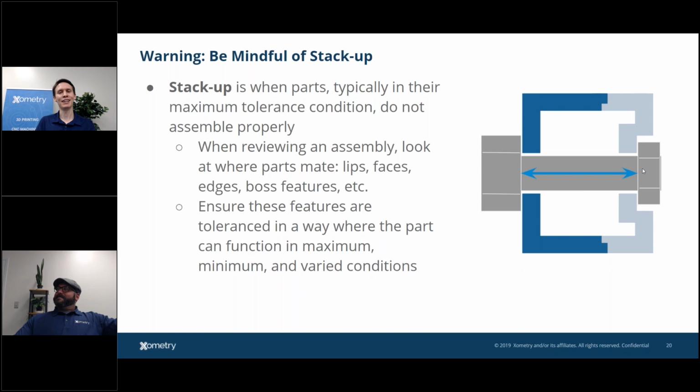Oh, actually, the other thing is parts are not always made in the same location. So a lot of times the testing of those final pieces and how they integrate together, especially from various processes like a mold part, machine part, sheet metal part, if they're all getting made together, the first time they may be together in one place could be at your doorstep. So just understand, again, that's why GD&T exists.